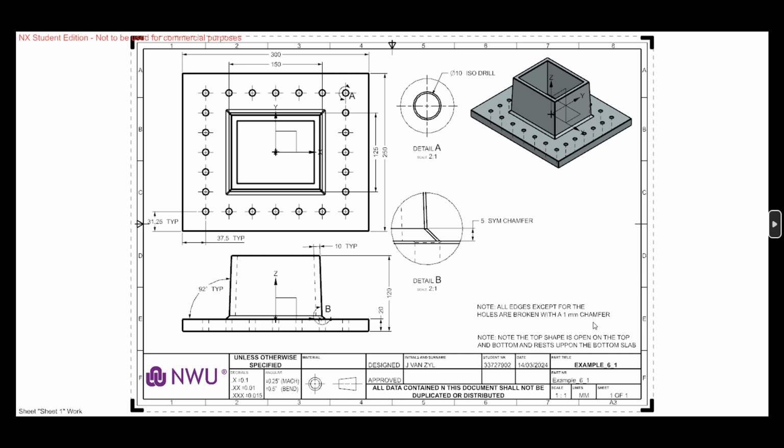So that's after you've built something, especially if you've built it from let's say sheet steel that got welded together, or parts that got machined or so on, you get rid of any burrs. So you just take any sharp edge and just run it over with an angle grinder or something, just to break that edge, so that your customer doesn't cut their hands on it.